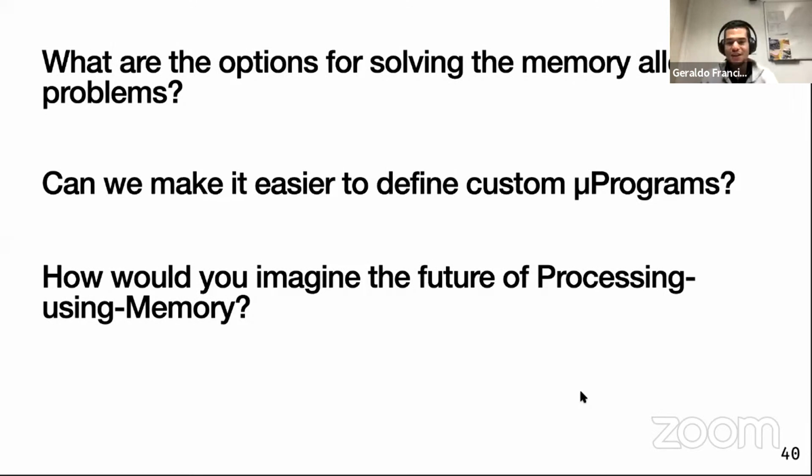So at some point, you're going to need that bandwidth available in the subarray, and all of those mechanisms are already processing using memory, right? We are talking about exploiting the organization of the subarray, exploiting the DRAM cell to do some computation. If you already have something like UPMEM, that Juan presented in some lectures ago, or some modern processing near memory solution, you already have the DRAM. You already have the capability of enabling SIMDRAM or Ambit or RowClone.